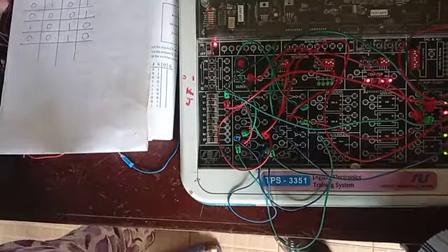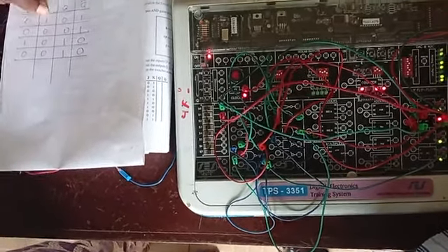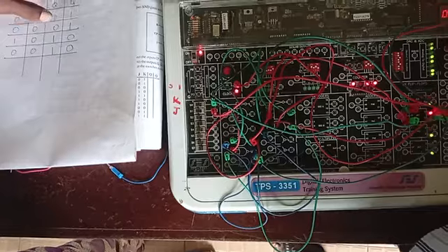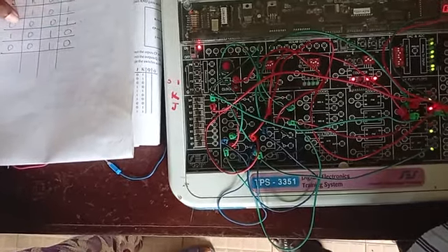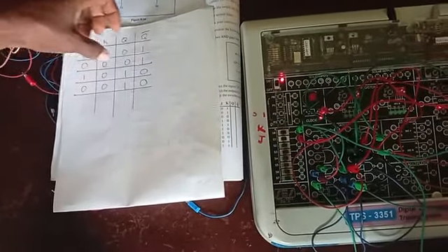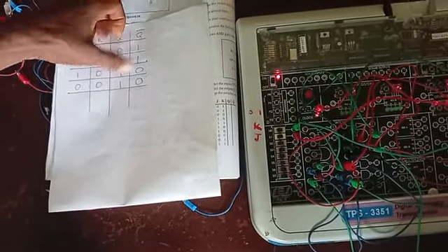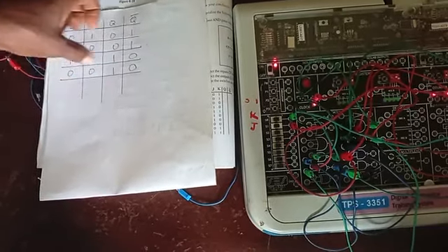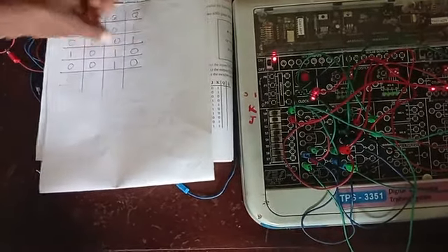So when you change any input, it's going to give us an output. Even if the input later changes, it will retain that. If at the end of the day we don't have any input, it will retain the last memory. If you put any input, it's going to bring out that output. If you remove the 2 inputs, it's going to retain the last memory. This is the table we are going to use to fill this table here.